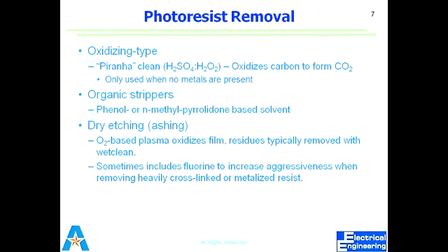When we discuss the etching process, you'll come to know the benefits and drawbacks of wet etching and dry etching. They have their own limitations and benefits over one another. But right now, dry etching is also one of the processes to clean the surface, and in that case, oxygen plasma is actually very energetic oxygen ions. They strike the surface and remove a very thin layer on the top. But of course, as the process suggests, it can damage the surface of the wafer as well.